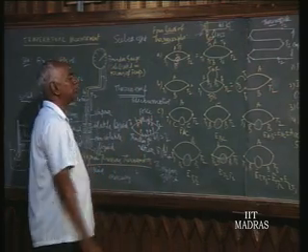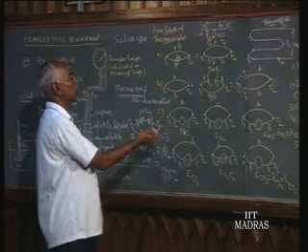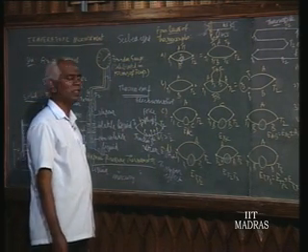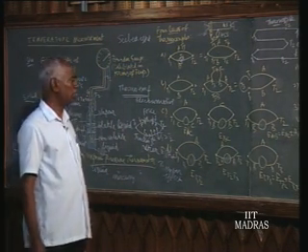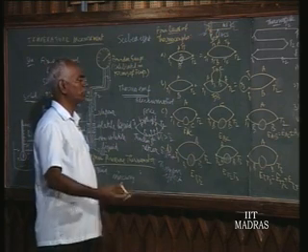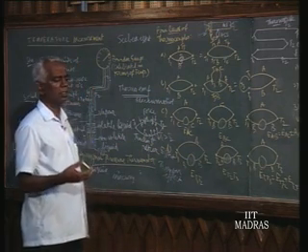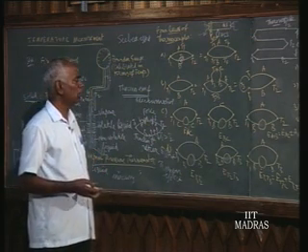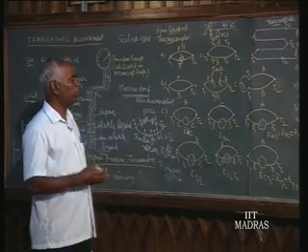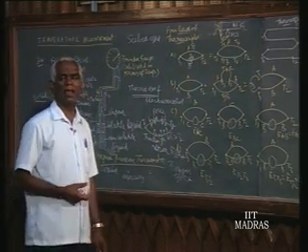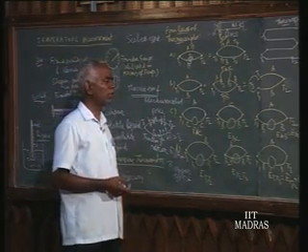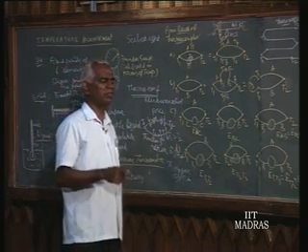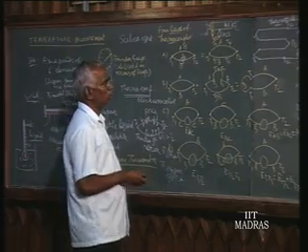The third law states the calibration of the thermocouple elements, and we have got a number of elements exhibiting this thermo EMF property. Suppose 10 elements, then by permutation combination, you may get hundreds of combinations with these 10 various elements. And calibrating each pair is a very laborious and time consuming job. So what is done normally is each material is calibrated with platinum.